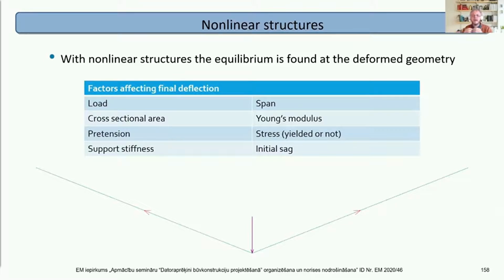So, for example, a cable might start off perfectly straight, but we know that it has no bending capacity, and therefore, under a linear analysis, has zero resistance. The reality is we know that it does carry load, but it will sag until we've got that V, and then the axial loads will be generated, and it will carry the load.